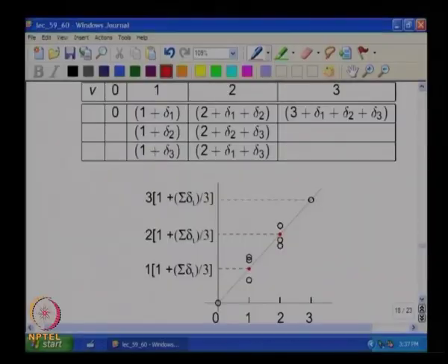So, if you consider a 4 level DAC with 3 unit elements, when the code is either 0 or 3, there is only one way of choosing the elements. When the code is 0, all elements are off.